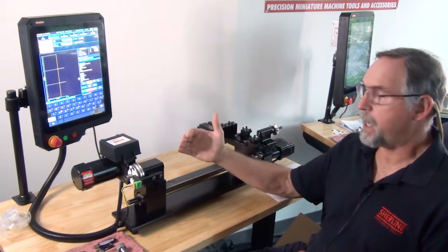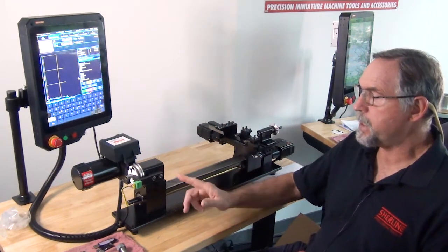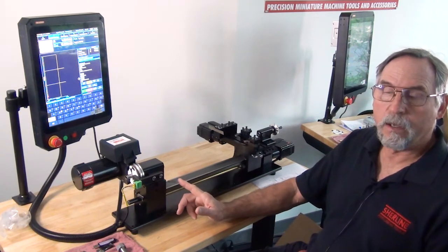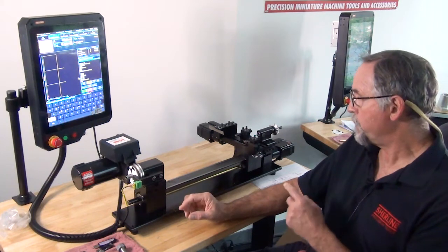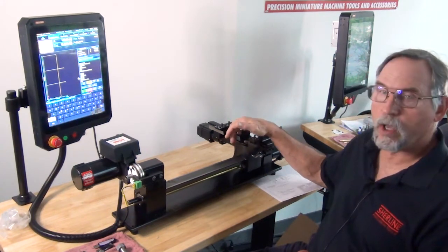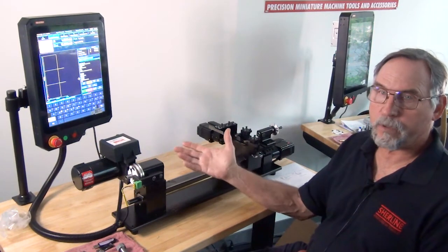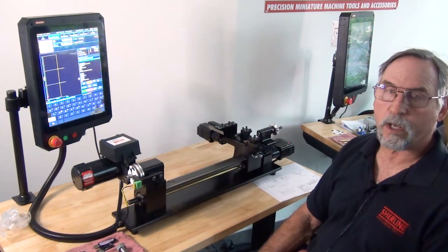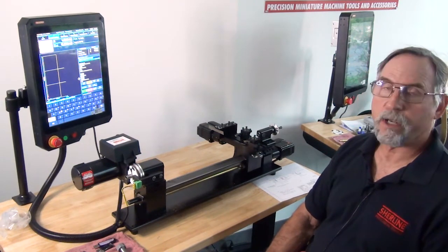The converse of that is if I have an RPM that's too fast, my feed and speeds at the outside are most likely going to be way too fast, which means I'm going to start burning the tip of my cutting tool off. I'm going to get blue chips. And then as I move into smaller diameters, then that RPM range is correct. So the G96 comes in very handy.